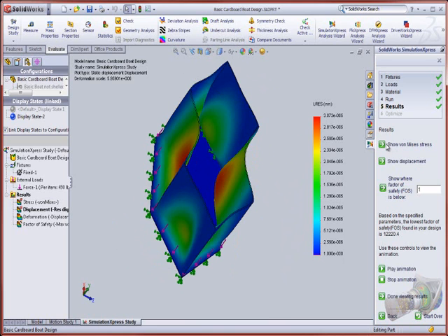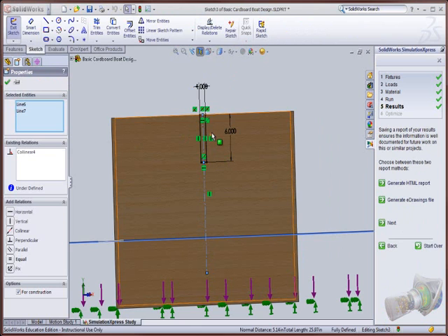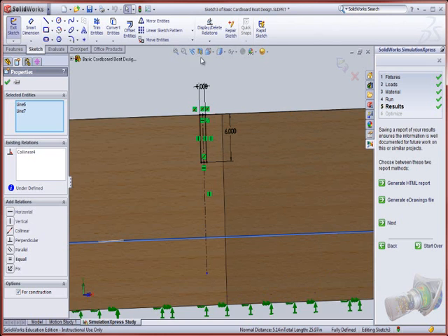So let's just go ahead and do that, and then we'll just run this animation again and see what it changes. Okay, so I've created a sketch inside the boat here. I've constrained it to the center of this part, and I made it 1 inch thick and 6 inches wide, which is kind of a little overkill, but it's almost easier to make it bigger using the cardboard and duct tape than smaller. I created a section view there, so I'm going to go ahead and exit that sketch.